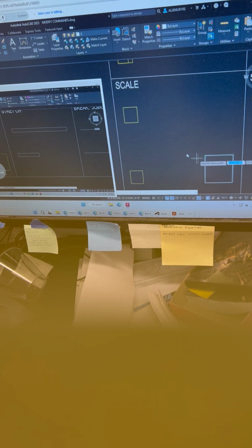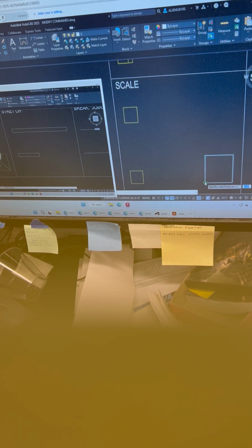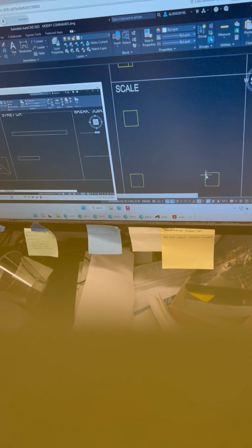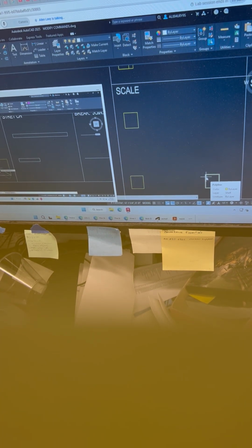I want the length of the bottom of this rectangle to be 3 feet, but I want to maintain the same aspect ratio, or the same size or spacing of the rectangle. I just want to scale this thing up so that this side is 3 feet, not 2'2" and 59/128. Okay, how do I do that?